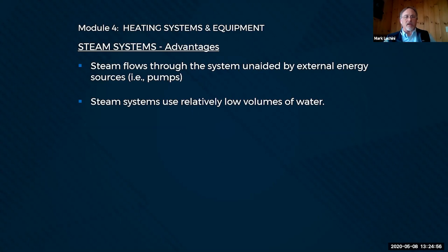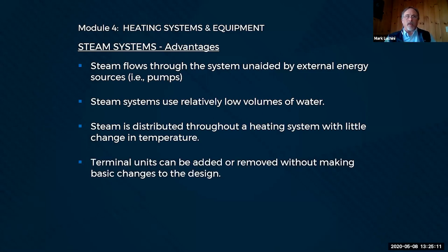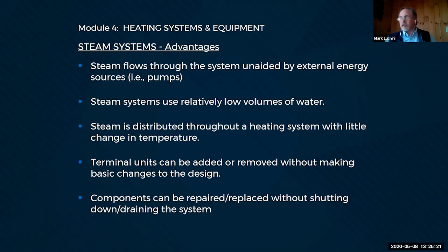Steam systems do use relatively low volumes of water, and the steam that hits the first radiator is typically the same temperature as the steam that hits the last radiator. Can't necessarily say that about a water system. With a steam system, you can add or remove terminal units without making any basic changes to the design of the system. And you can shut down a portion of the system and leave the remainder of it open much easier than you can with water systems, where you typically have to shut down and drain the system to add something to it or take it apart.